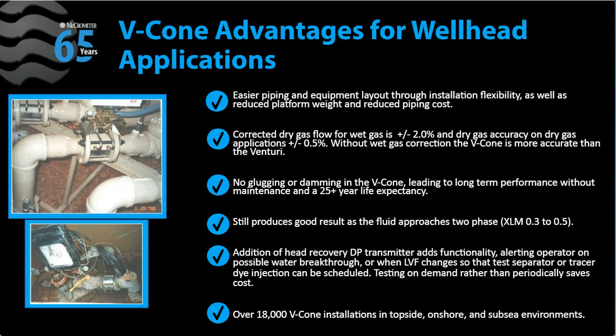And you can add a head recovery DP transmitter to add functionality, and this alerts operators to possible water breakthrough or when the liquid volume fraction changes, so that the test separator or tracer dye injection can be scheduled. Now, testing on demand rather than periodically is going to save operators a lot of cost. If they have a proven meter with a stable signal that can alert them immediately whenever the LVF changes or whenever there's a water breakthrough, they can change their control.